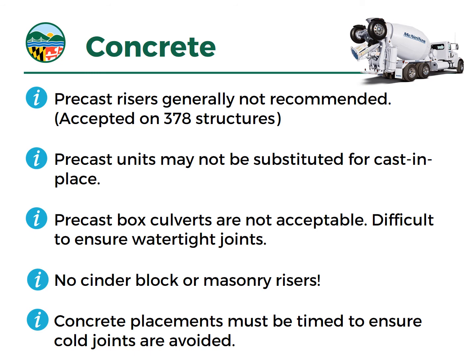We understand that there are some better methodologies, some better materials out there that may make these precast structures less prone to leakage. But I think the burden is pretty big to get us to approve these at this time. So maybe someday, but I'm not sure we will anytime soon, particularly with precast box culverts, because of the issues we've seen. I've seen a few photos of them, but never in person, of cinder block or masonry risers. That is definitely a design no-no.